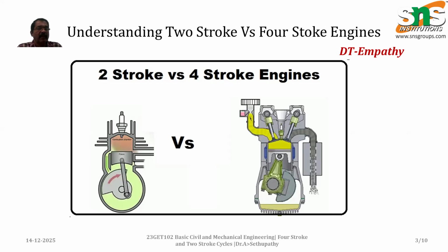Air is drawn into the combustion chamber as the piston moves from top to bottom. After that, the inlet valve closes, and the outlet valve is already closed. The piston moves to the top side, so the air is compressed and reaches a high temperature. At that time, the fuel injector injects fuel into the combustion chamber.